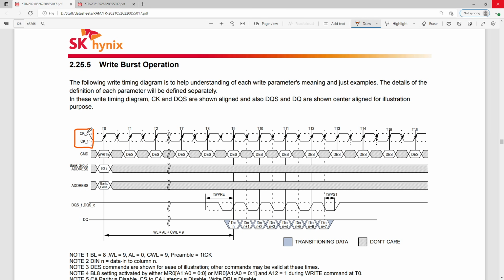And this is measured in hertz. If you're going to talk about the memory clock, you should use hertz for that because it's literally a clock. That's the whole point of hertz, to measure frequencies. So if you have a DDR4 3200 kit, it will have a 1600 megahertz clock, as in this signal right here is 1600 megahertz. You could take an oscilloscope, admittedly a pretty expensive one, and measure this, and it would be 1600 megahertz. So that's physically there.